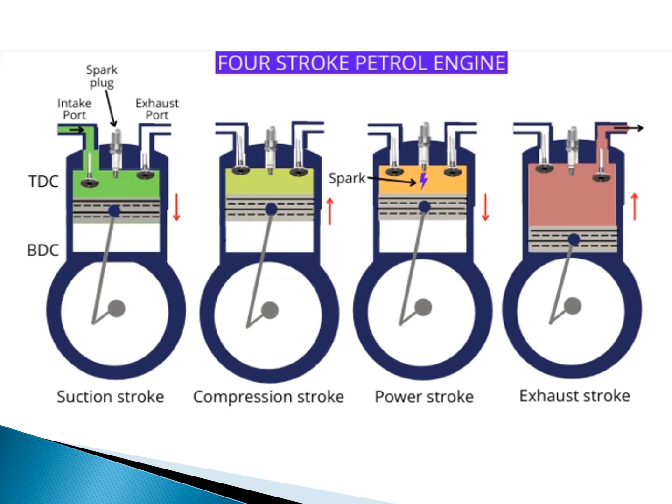And these combusted products, that is the polluted products, the soot and everything after the burning, the exhaust products will be going out through the exhaust port. And as the piston reaches the TDC, the top dead center, all the exhaust particles will have escaped through the exhaust port. Again the cycle begins, that is the first figure, the suction stroke.